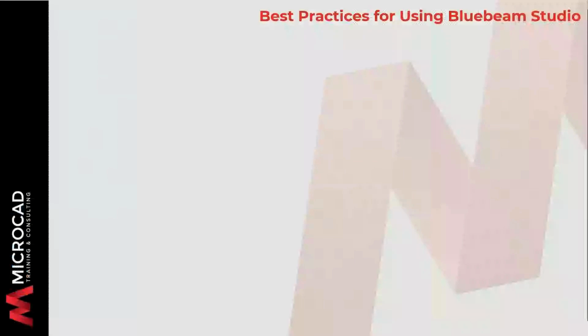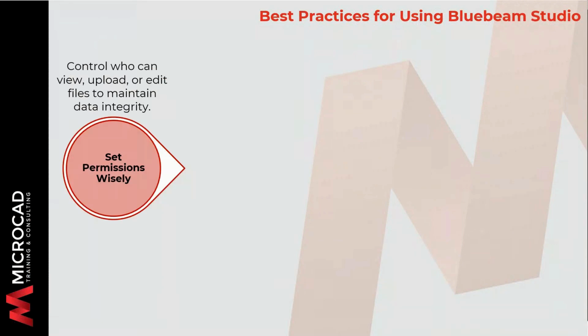And now, as we wrap up, I'd like to leave you with a few best practices for getting the most out of your Bluebeam Studio. So first, make sure that you're setting the right permissions. Whether it's a session or project, that helps you keep your documents secure and ensure the right people have the right levels of access.